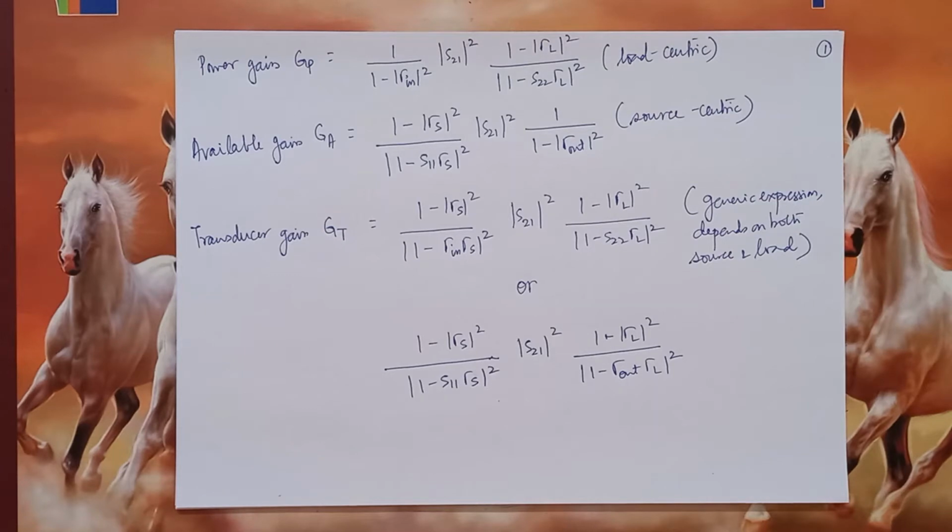Having said that, there are some issues which we need to consider for amplifiers in particular, which we don't consider for other RF circuits that we have discussed so far. And we are going to talk about those considerations. Why? Because amplifiers are active circuits. They have the potential to take some input and provide an output whose magnitude is larger than the input.